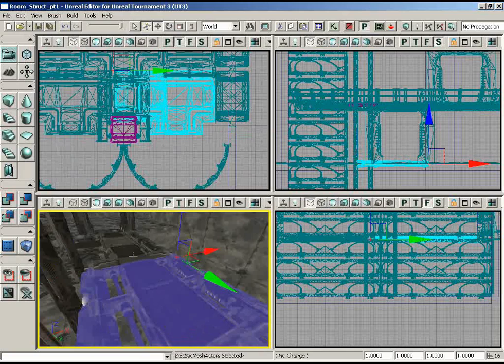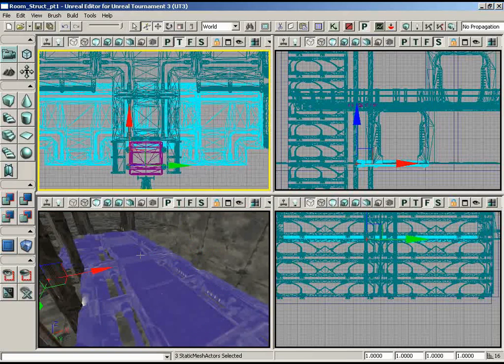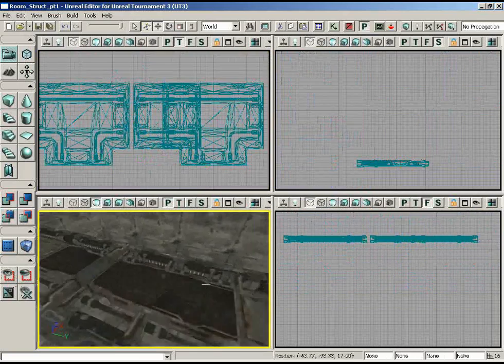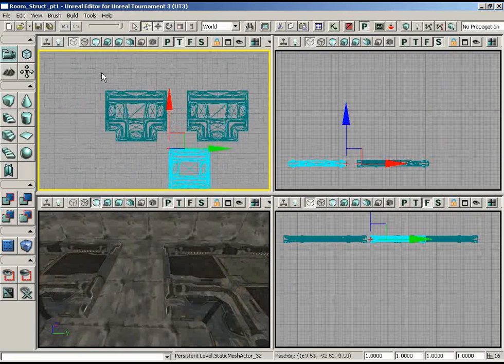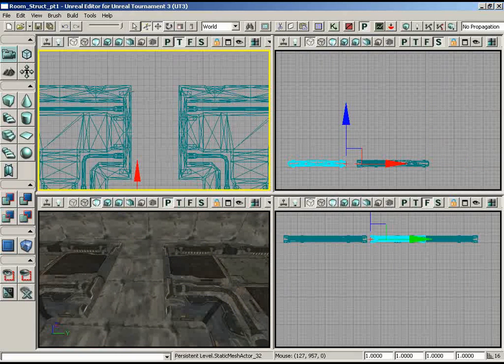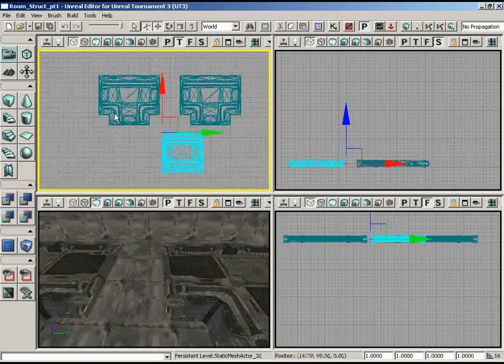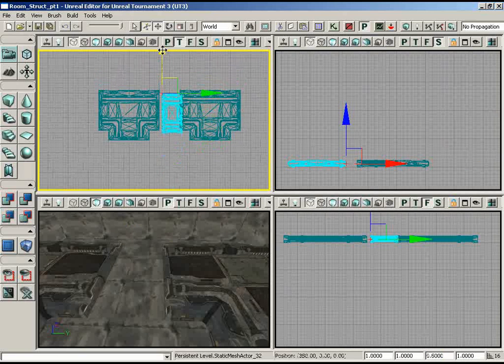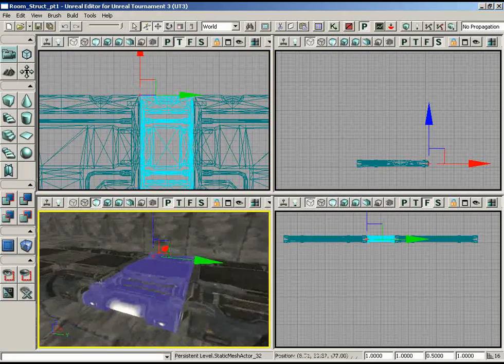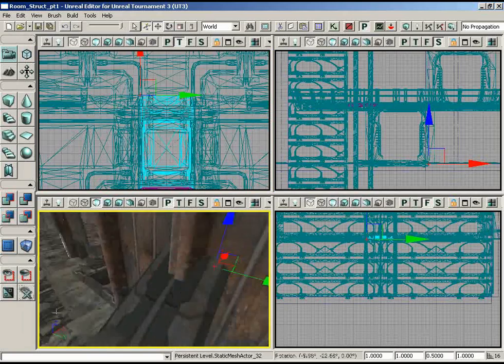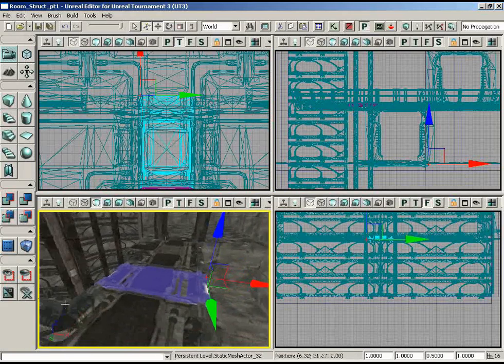So what we can do, since there's a lot of meshes in this area, I'll grab just the 3 walkway meshes, show only those meshes, and then you can move this out of the way so I can find the distance in between the two, which is apparently going to be a very short distance of 128. So let's set the scale down to 0.5 for this brush, slide it into place, something like that, and we can show everything again. And we've got the nice walkway working there.